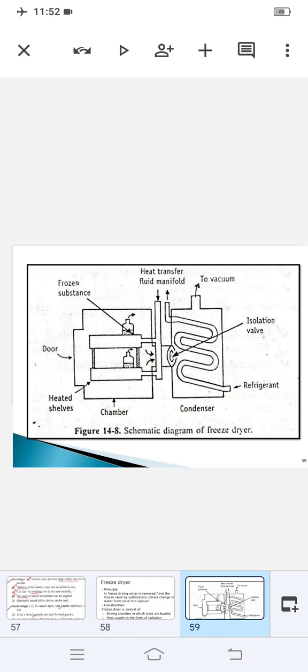Second one is pre-freezing to solidify water. So the vials, ampoules or any bottles in which the aqueous solution is packed are frozen on the cold shelves. Okay, the temperature of that is about minus 50 degrees Celsius. And what happens during this stage? The cabinet is maintained at low temperature and atmospheric pressure, and the normal cooling rate is about 1 to 3 Kelvin per minute, so that large ice crystals with relatively large holes are formed on the sublimation of ice, okay. This is also responsible for giving us a porous product, okay.